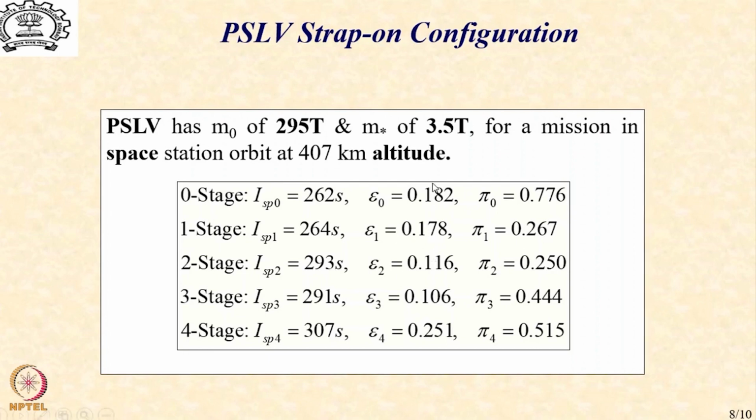There is no great difference, and that's what you will find in most launch vehicles, that the booster stage and the first stage typically are of similar configuration. Sometimes the first stage inventory can be used also as a booster stage, so that you don't have to design a booster stage separately.